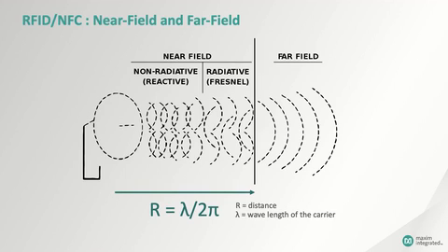The near-field region can be further differentiated into two subregions: the reactive region, where the receiving antenna has a significant impact on the performance of the transmitting antenna, and the Fresnel region, where the inductive effects of the receiving antenna have less effect on the transmitter. The specifics about exactly how antenna placement affects system performance is pretty far outside the scope of this discussion, but hey, there are lots of online resources on this topic if you'd like to go further.